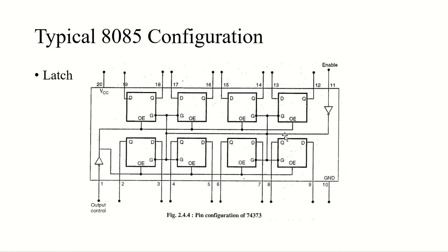It is an 8-bit latch. It has the D-type flip-flop and provides the buffer controller input, so it is providing the controller input to the buffer. It provides a choice of 8 latches or 8 D-type flip-flops in a single package. As you can see here, we have 1 2 3 4 5 6 7 8 D-type flip-flops in one package. And it has tri-state bus driving output. It has full parallel access for loading. It has a buffered control input, and it has PNP input that reduces DC loading on the data lines.